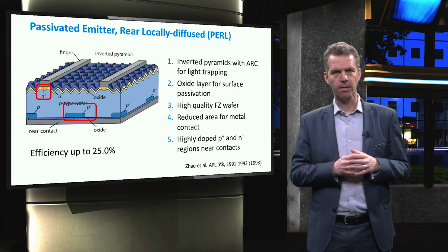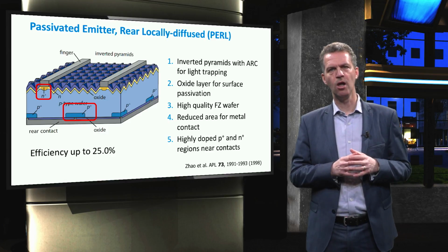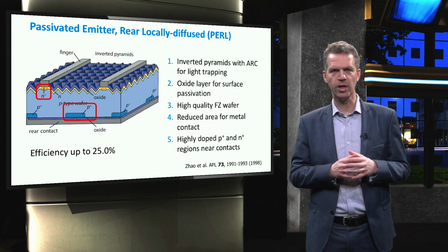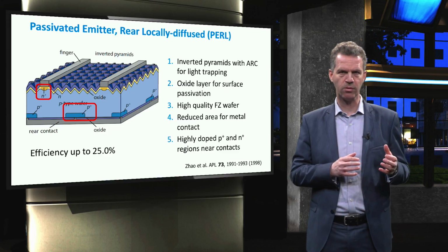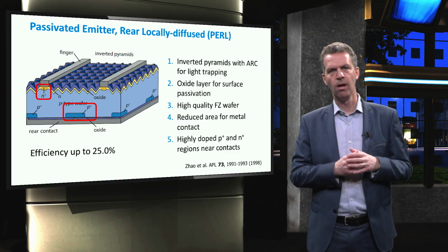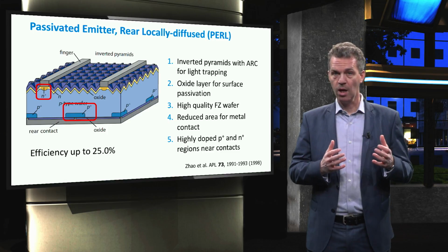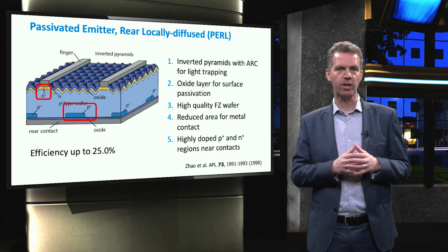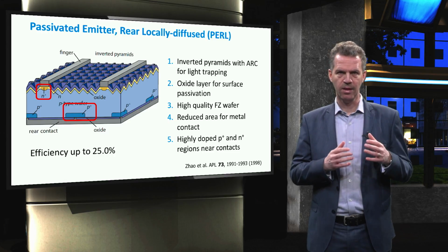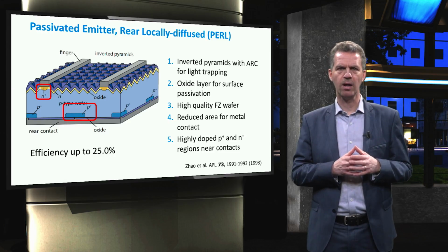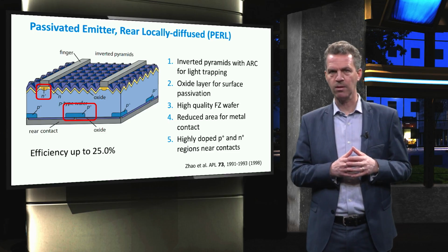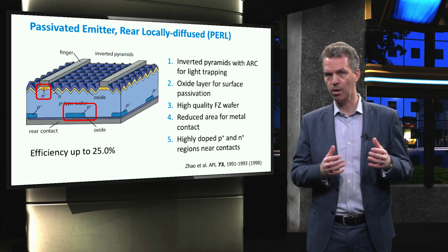Finally, the metal semiconductor interfaces feature locally increased doping to create a selective emitter at the front contact and a local back surface field or BSF at the back contact. The highly doped P-type region that creates the back surface field is in this case obtained by boron diffusion that was patterned on the cells before applying a metal contact.